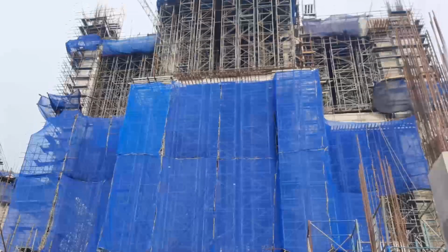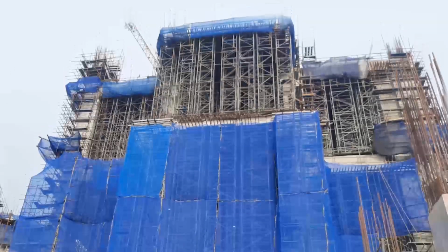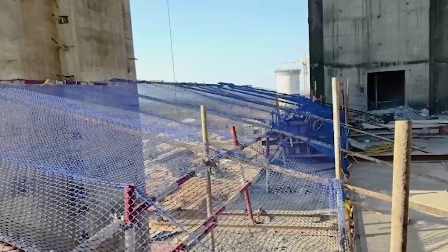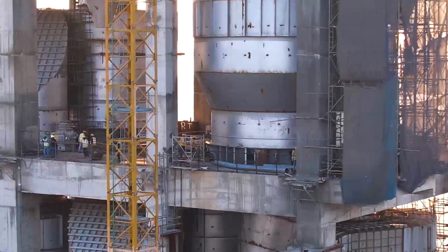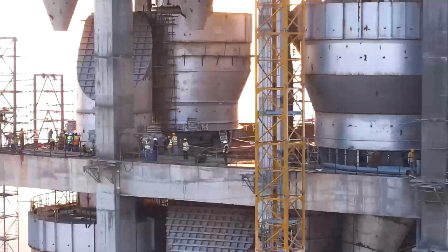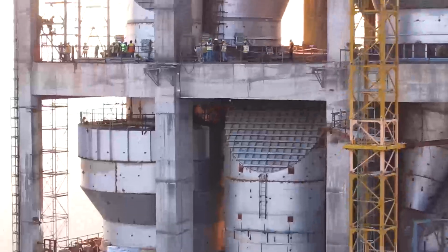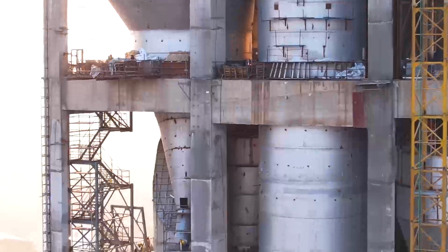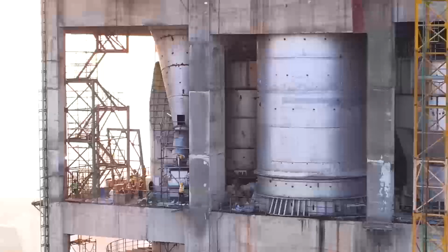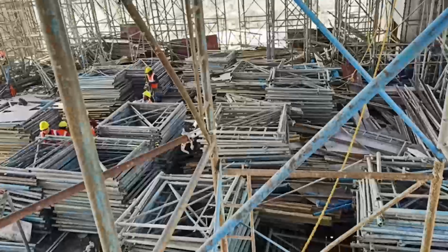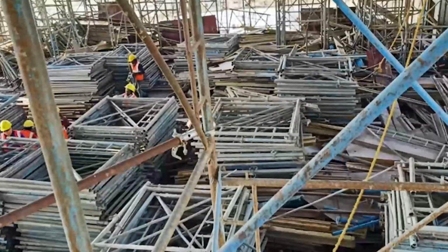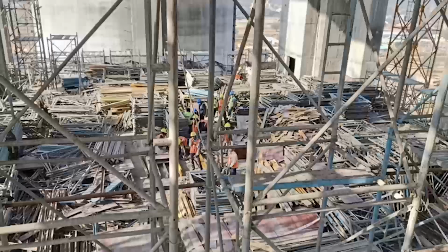Provide vertical safety net from floor to floor. Catch net below the working floor to contain any falling material. When the floor-to-floor height is more, length and width of the floor is less in preheater building, so space will be more congested. For casting the next floor slabs, the existing floor slab is the space for stacking the materials and to erect the shutter supports.